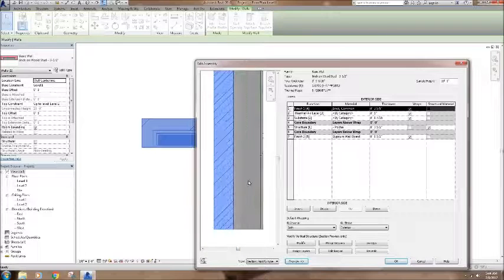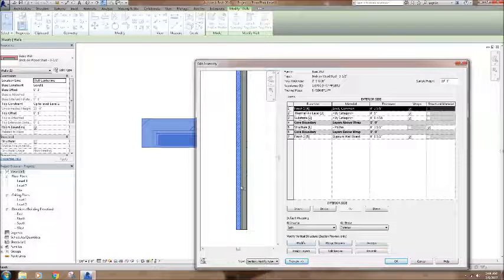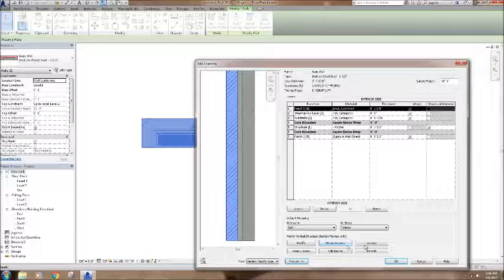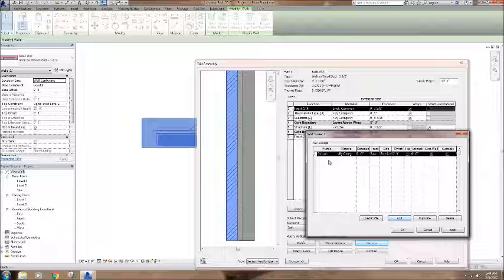So what this is for is all these tools here. You can insert sweeps, you can insert reveals, that sort of thing is something that you can build into the wall type. So if you have a situation where maybe you have a flat site and you're running with a brick wall and it's got a sill that sits on top of the brick at about 3 feet, something like that, we can come in here, hit sweeps, and then hit add a sweep.